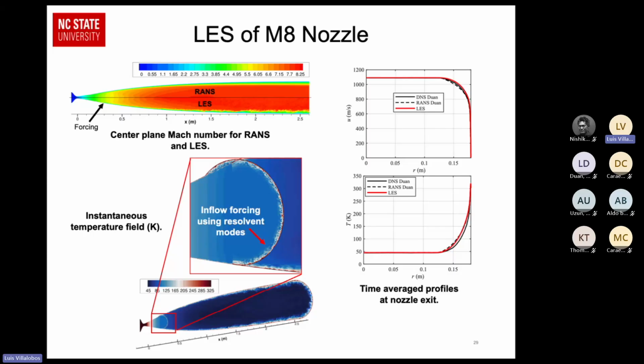It's like making a little fake wave region above the boundary layer. There was this fake region of really high eddy viscosity that we tried to put a little transition model in and do something to get rid of, but we couldn't. And even with the real random forcing, it also screwed that up. It screwed both of them up, having that excessively high TKE sitting in the middle of a more or less uniform flow.